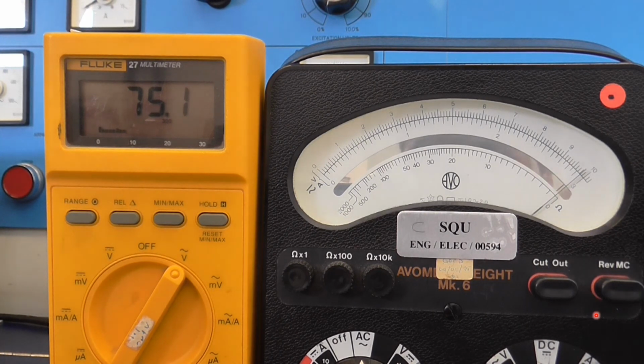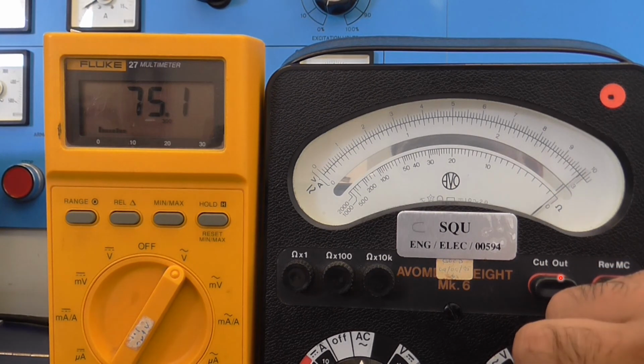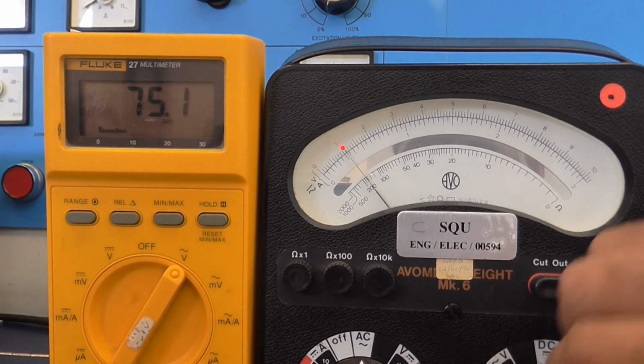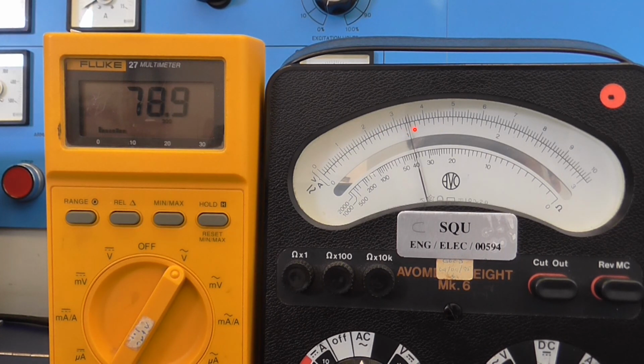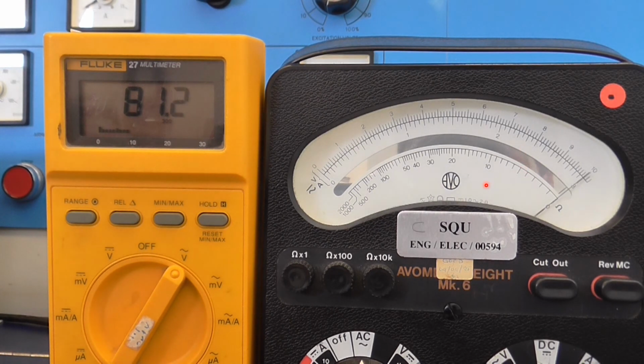Let's change the scale of the meter so that we can see more. Now the scale is at 1, so this is 0.1 amp or 100 milliamp, 200 up to 1000, or 1 amp. You see now by a small change in the voltage we have a high change in the current. Once we enter the saturation region, I want you to listen to the sound of the source. Can you hear the sound that the source is making? That is when we enter the saturation region.